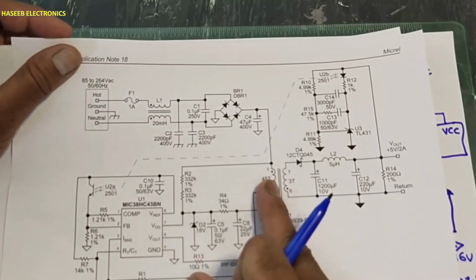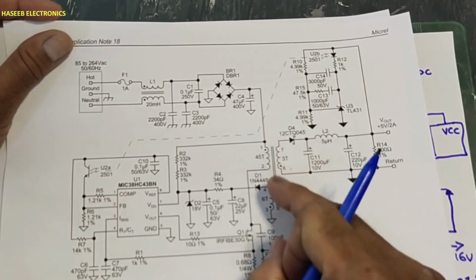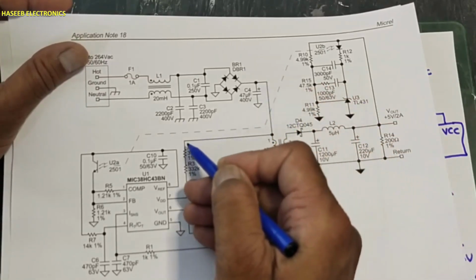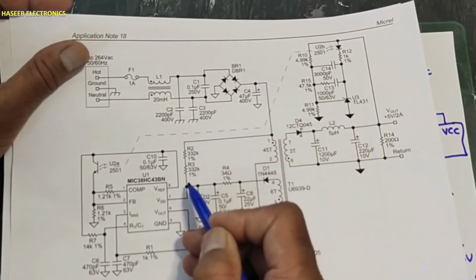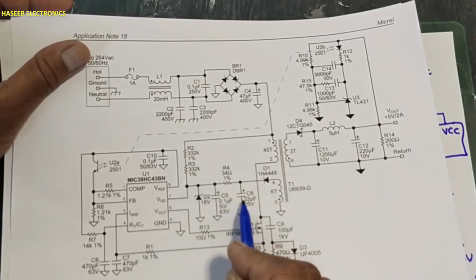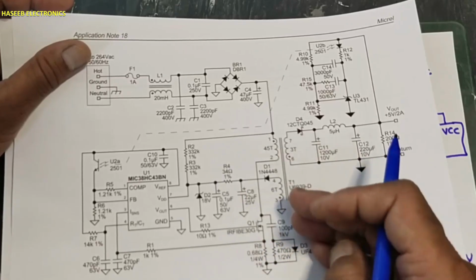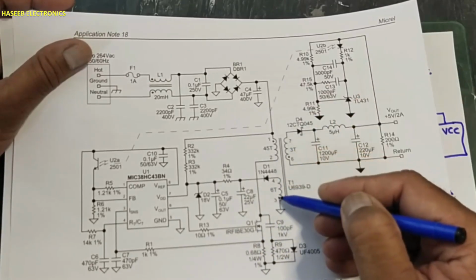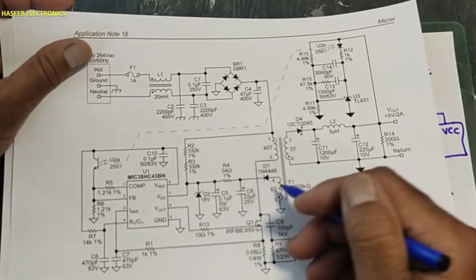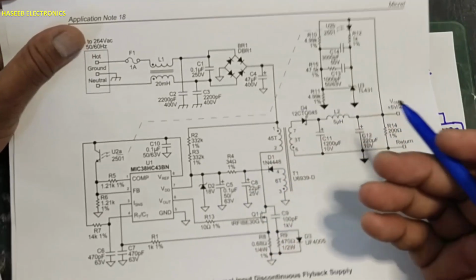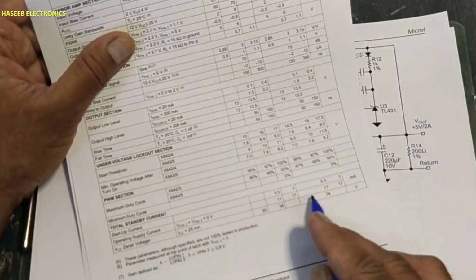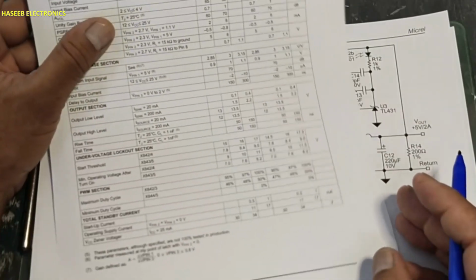When we are switching, the voltage is transferred in this winding and this winding. At initial startup, positive voltage is derived through these startup resistors, and they charge this VCC capacitor. But when the circuit starts, this winding will provide voltage to this capacitor, and it is capable of providing more than 17 milliampere, that is, the operating supply current of 11 to 17 milliampere.